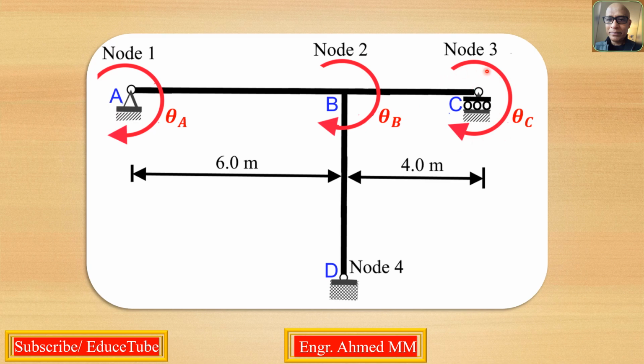Already I showed arrow marks here to show that it is free to rotate or free to move. So 1, 2, 3. How many did we get? These three places are free to rotate. So there are 3 degrees of freedom.